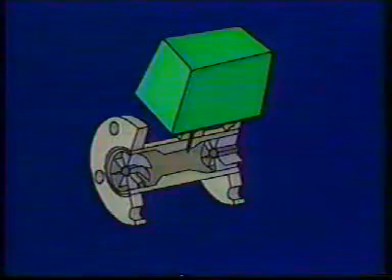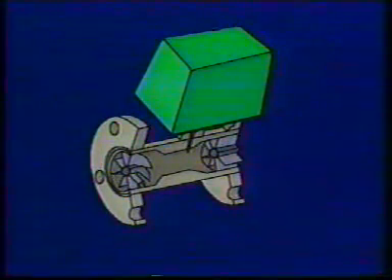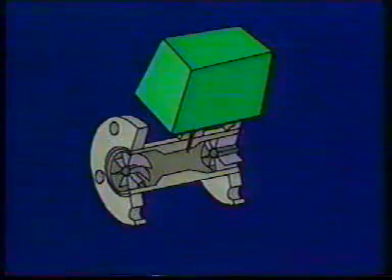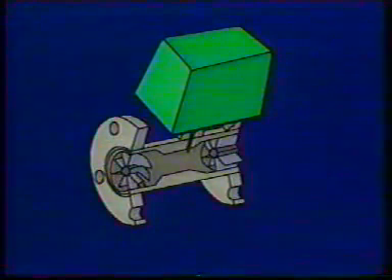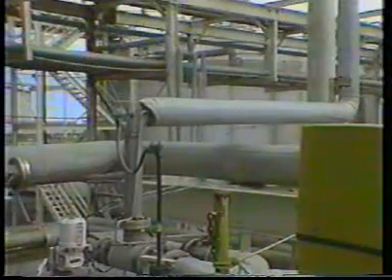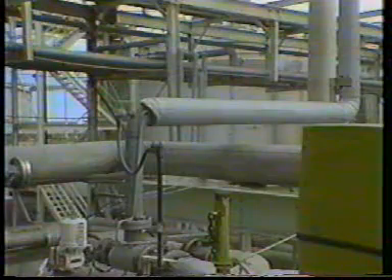The vortex precession flow meter has an overall accuracy and range comparable to the vortex shedding flow meter. However, it does have one major disadvantage. The pressure loss that occurs when using the vortex precession flow meter is about 5 times greater than with the vortex shedder. As we've seen in this program, there are many factors that must be considered and compensated for to